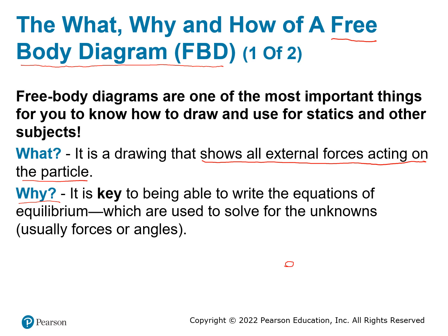So if you focus on this point here, you can find several different forces acting on this point, and if that is the case, then you can use summation Fx and summation Fy to solve the problem, right? So when you draw this, make sure that you draw the angle if the force is not along the x or the y direction.